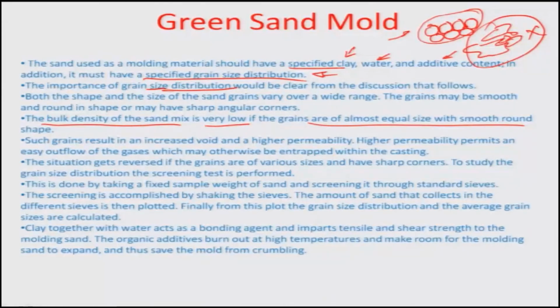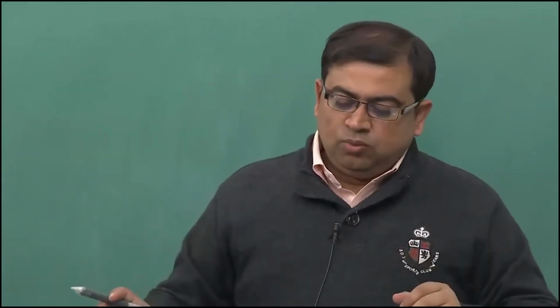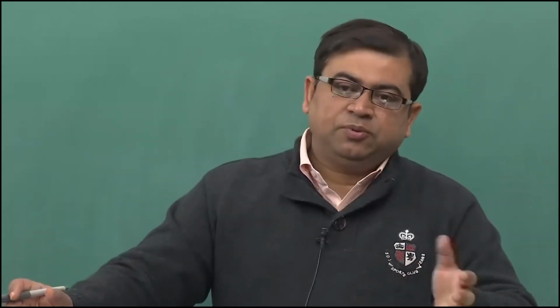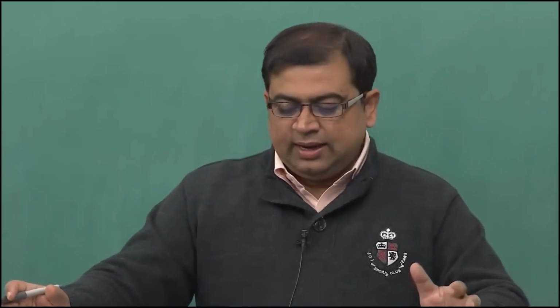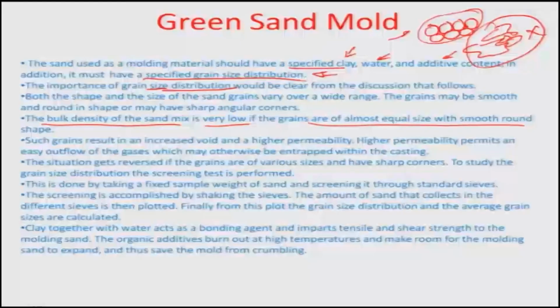Obviously, I have no need to reiterate that at a higher temperature the sand expands and it looks for those voids where it can get into without breaking the mold. So, you are giving porosity just for that purpose, and you are actually creating it using some kind of additives, which vaporize and create these pores, so that there is no problem of the sand expanding and breaking the mold.